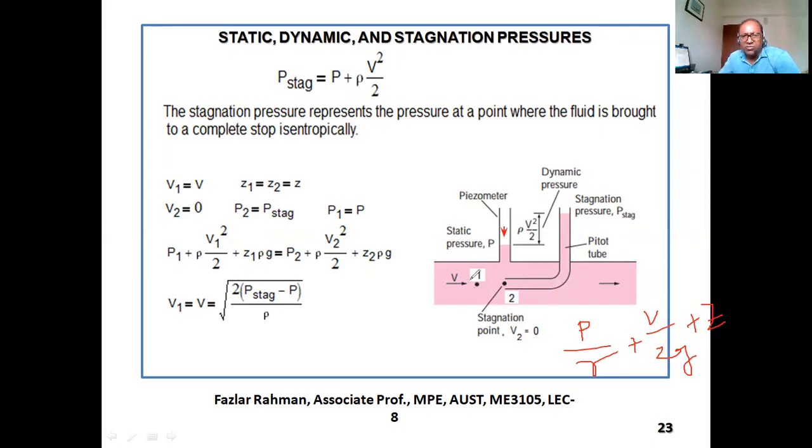So you see fluid moving along this direction, right? Over here what happened? Fluid is still moving. So due to this pressure component, the fluid tries to get out from this piezometer, tries to move in the upward direction. But atmospheric pressure is pushing it down. If the inside pressure is higher than atmospheric pressure, then the height of the fluid is increased. So that's why you see a little bit of deflection in the fluid element, the mass deflection.